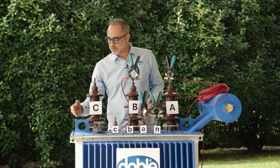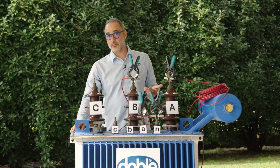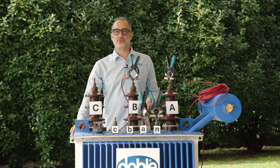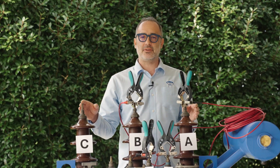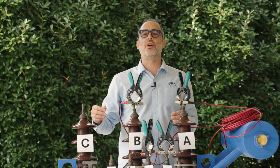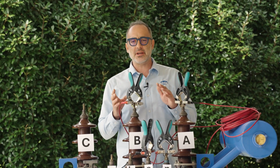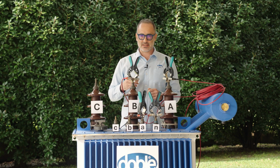Let me first present to you our little blue transformer, the little blue. It has the power of 100 kVA, and on the primary side it is 18.5 kilovolts, and on the secondary side we should measure 400 volts. So the ratio is about 80. That's what we will see later when doing the test.